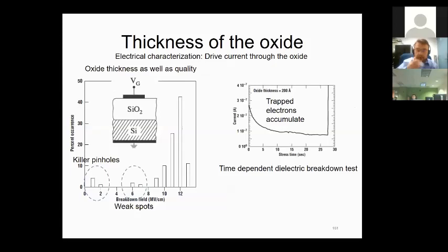All right. So there are other ways to characterize the silicon dioxide. We just looked into the non-destructive optical way, but there's of course an electrical way too. In that case, you have to create the same configuration that we worked on before. You need to have a metal, an electrode. It could be polycrystalline silicon too, but underneath that, you can put your oxide, the thermally grown oxide, and we have the semiconductor. Again, it's the same MOS structure, metal oxide semiconductor structure.